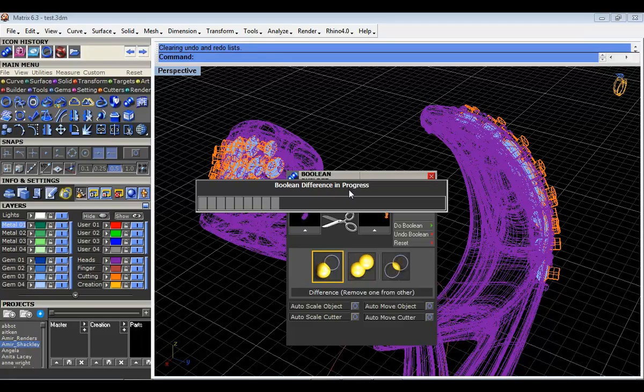I also, to be able to use a tool to its best, you've got to realize what it is good for. So high precision work is feasible inside T-splines, but you need to remember that you're using T-splines inside Rhino, and why reinvent the wheel? You have all the Rhino tools at your facility, so use the right tool for the right job. Get the T-splines to build your organic stuff. Use your curves to start from, and you can get really good, high precision parts.